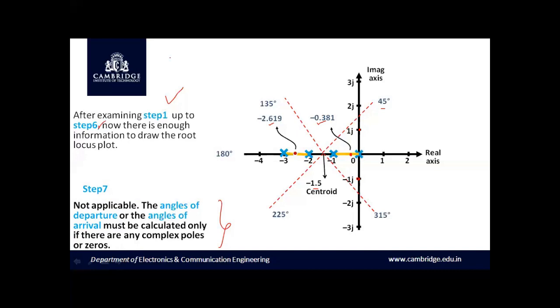As we know, when k equal to 0, we have a pole at s is equal to -1 as well as at s is equal to 0. When you keep on increasing the value of k, we can see the movement of the poles in this region of the root locus. These two poles will intersect at one particular point at which multiple poles occur at a particular value of k, and that is the place at which the breakaway point occurs.